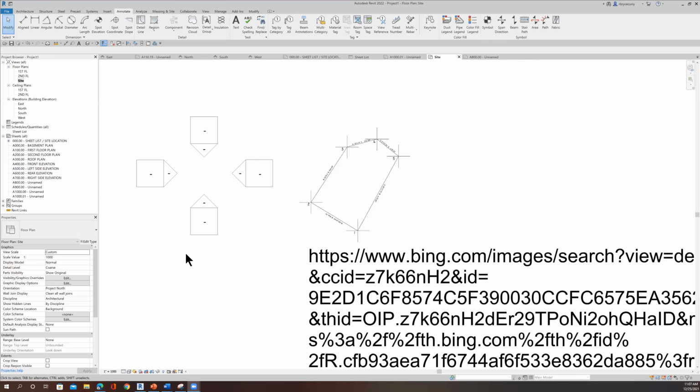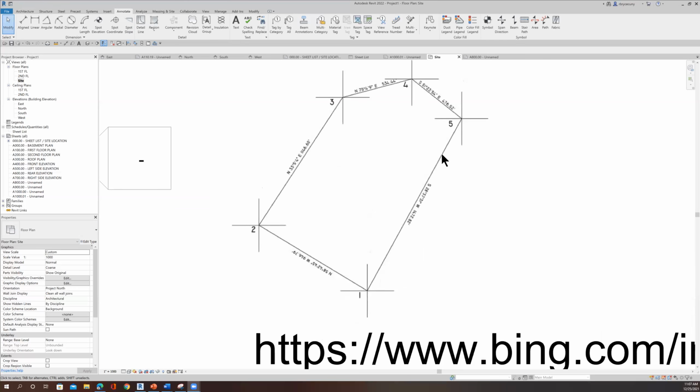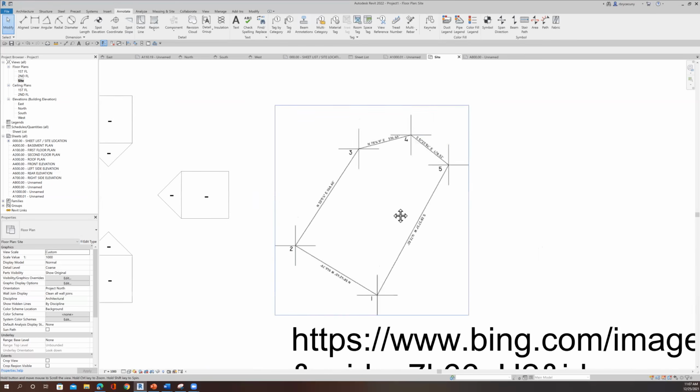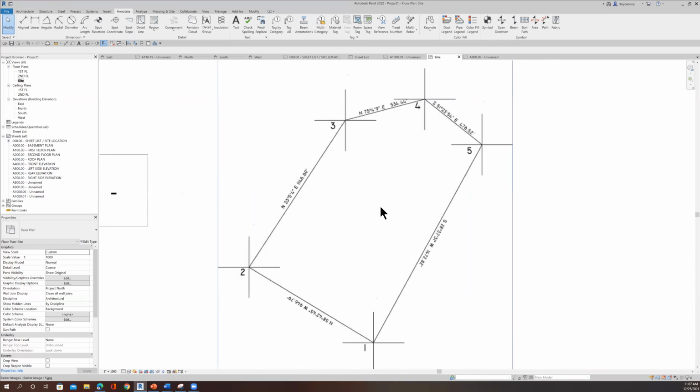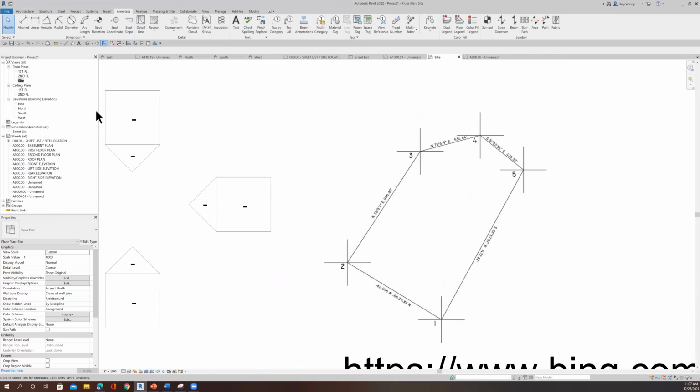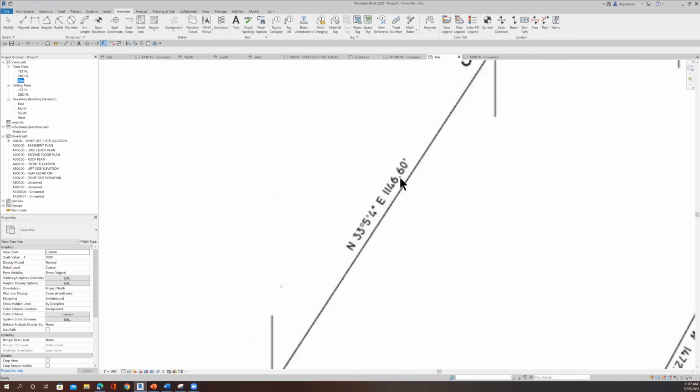Generally the client will give me a graphic like this, which I've taken from the internet, and here's the link to that. There'll be a PDF in the content area of Blackboard with that link and this graphic, so that you can use this graphic to duplicate what I'm going to do right now. But I'm at my site plan. The client may provide me with a visual like this, or they simply give me a legal description, which would include the lengths of the property lines, which are seen here, and the angle of the property line, which is seen here.